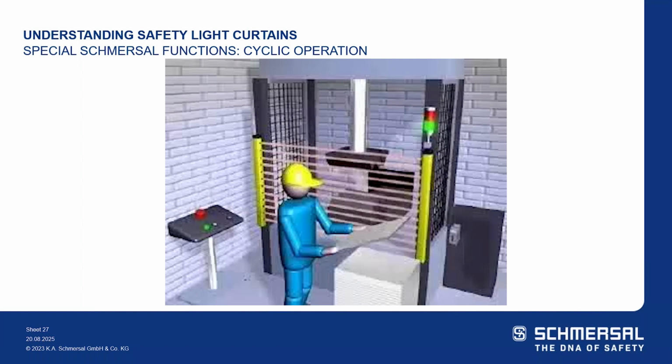I thought I would let that run through one time before I talked. It's also quite loud. This is cyclic operation or cyclic mode, also known as presence sensing device initiation. That allows the interruption of the light curtain array to trigger a machine cycle, allowing the light curtain to be used as a machine control device.